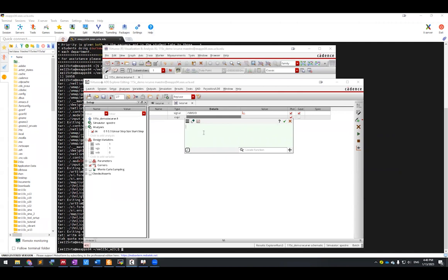The resistance is voltage over current, so we use the DC voltage, VDC, and enter. You can choose what kind of DC voltage you want to use. We want to use VDS over IDC, the DC transistor current, and then you can evaluate the value by pressing this button.